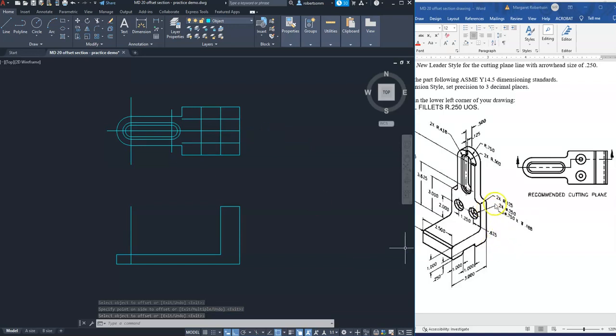Now these are counterbore holes, so the through hole is 1/4 of an inch in diameter, and the counterbore is 3/4 of an inch in diameter. I'm going to make the 3/4 inch hole first, the bigger hole first. It's easier to do that and then put the little one inside. And before I do that, I think I want to use the intersection here.